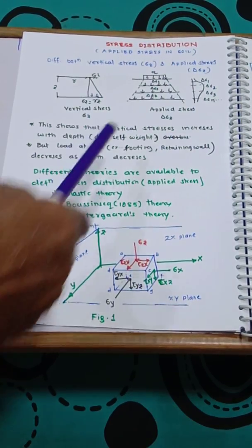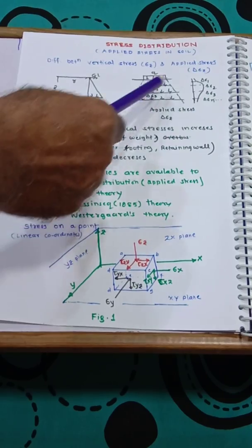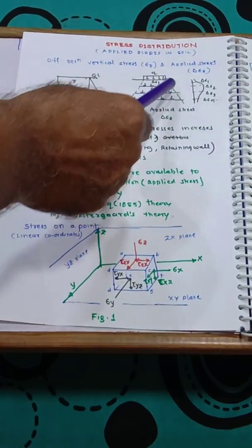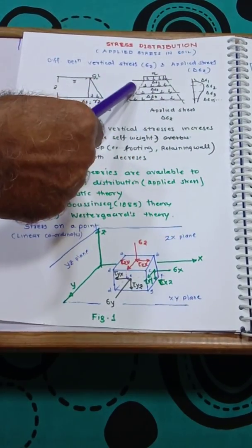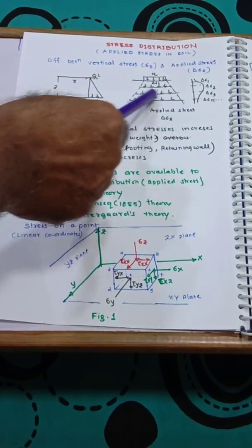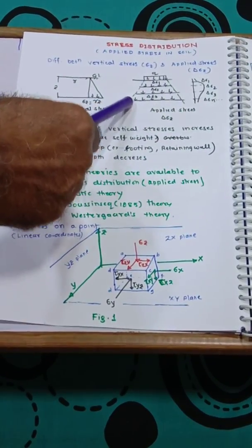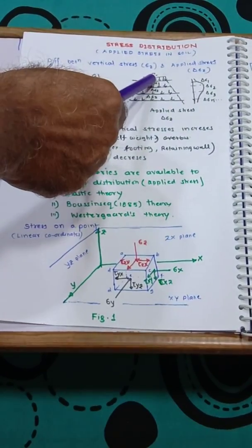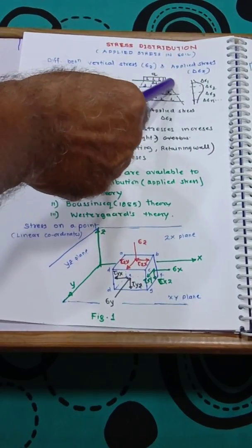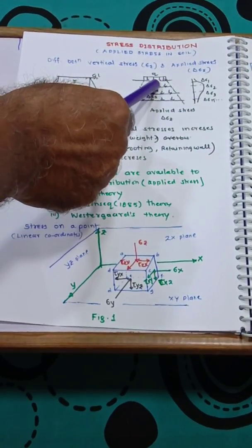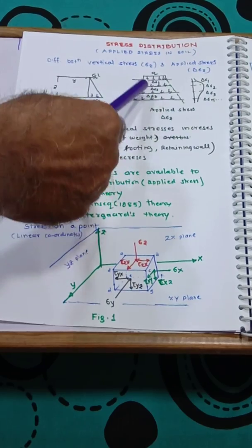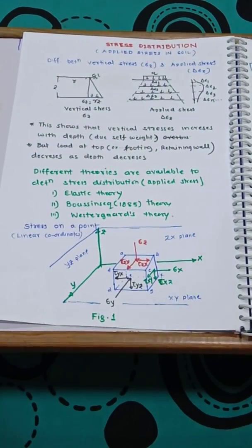Okay, you see here, it approximately disperses. As it disperses, the area increases, therefore load upon area, the stress goes on decreasing. It means the effect of this load on a particular level, maybe the surface or at a certain depth, goes on decreasing, and it diminishes after a certain distance.